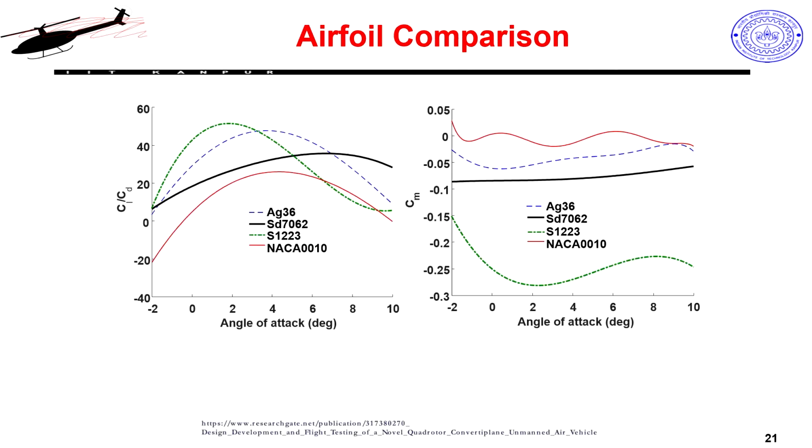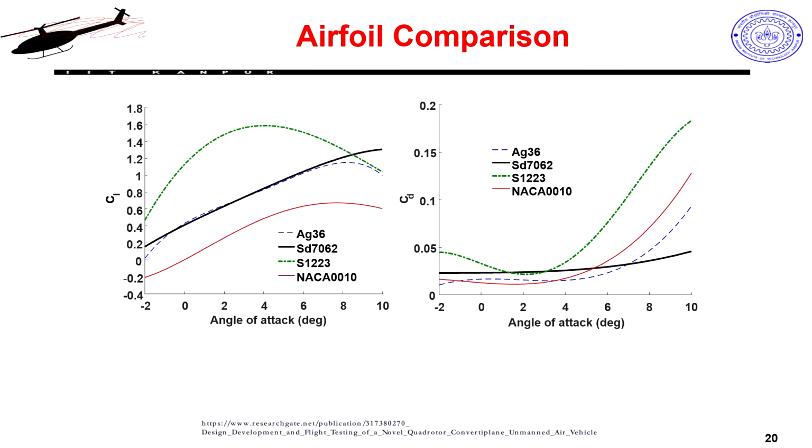So, let me go back to these other two graphs, which will hopefully give us some clue about that. Here I have put graphs taken from XFLR or Xfoil kind of software. These are panel method based software which can compute your CL versus alpha, CD versus alpha very easily and quickly for, I would say, moderate Reynolds number. They are not very accurate for high Reynolds number, and they are not very accurate for very low Reynolds number either. For moderate Reynolds number they are okay, they will give you reasonable answers.